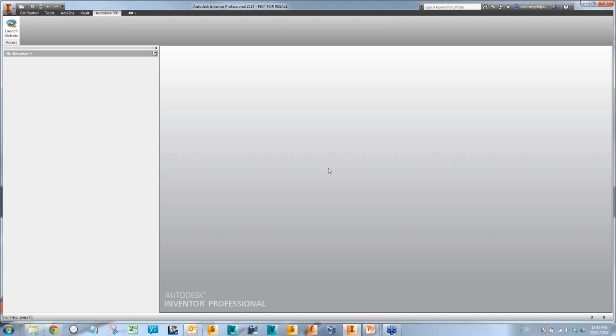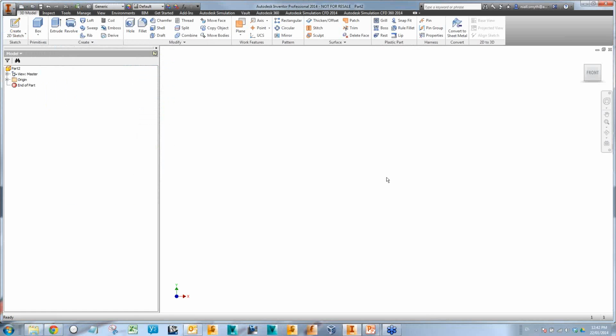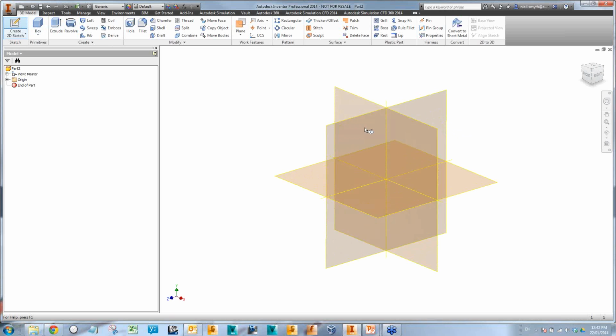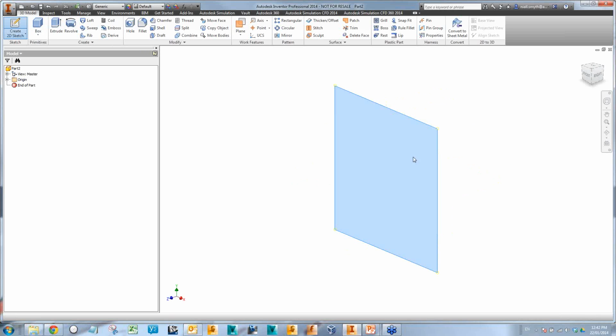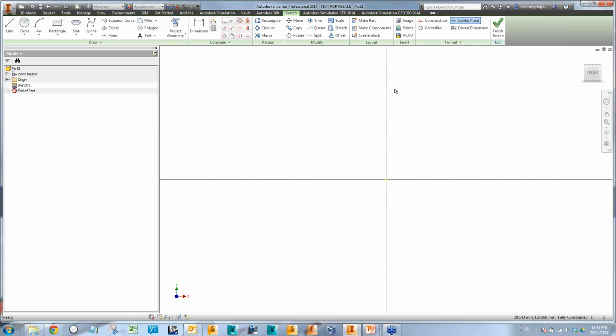Okay, so let's jump into Inventor, and we'll swap across here. For the master sketching example I'll start from scratch, and we'll discuss some of the principles of top-down design techniques. I'm going to start on my origin work plane and build an assembly that's going to look like a chute or a kind of funnel for maybe materials processing or whatever. So I'm going to start by creating a rectangle.